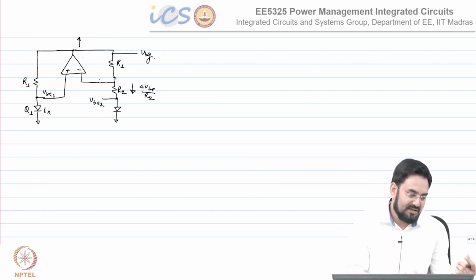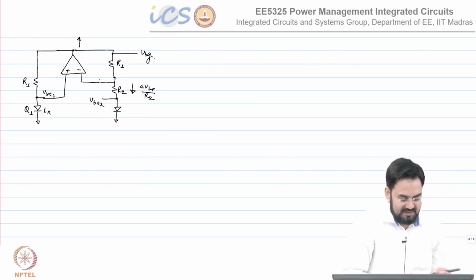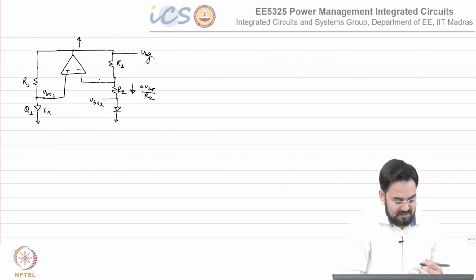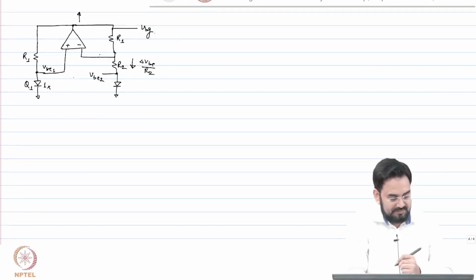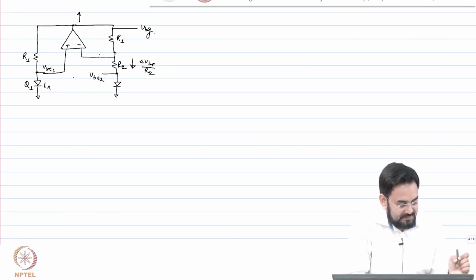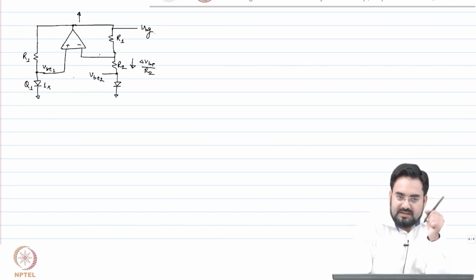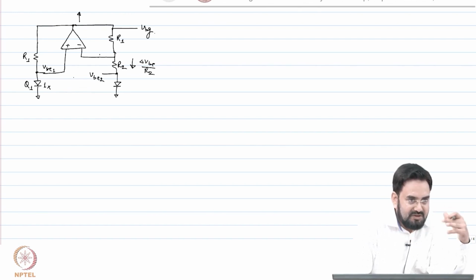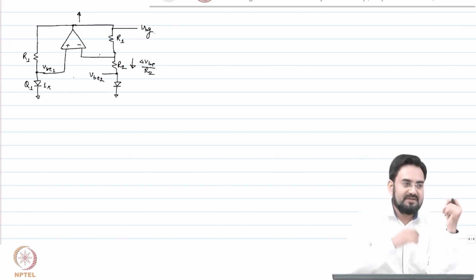So that is how you can find the sign in any feedback system without breaking the loop, you can find it intuitively. And if you look at the circuit I have drawn for linear regulators, the reference is connected at negative and feedback is positive. The reason is you have a PMOS at the output, so that is another inverting stage and you have to flip the input to make it negative feedback.